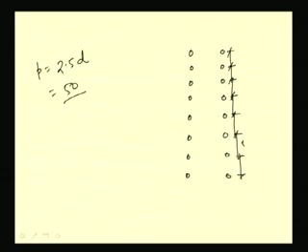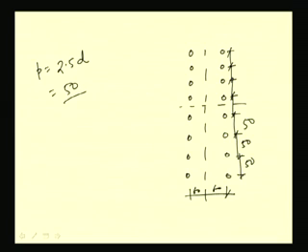So, these are the pitch distance. The pitch distance can be found from the codal provision, that is 2.5 d around we can make. So, this is becoming 50. So, let us take the pitch distance as 50, and this distance we have made 60, right. So, the neutral axis will be passing through this. So, this is 25, it should be 25, again 50, 50, 50.